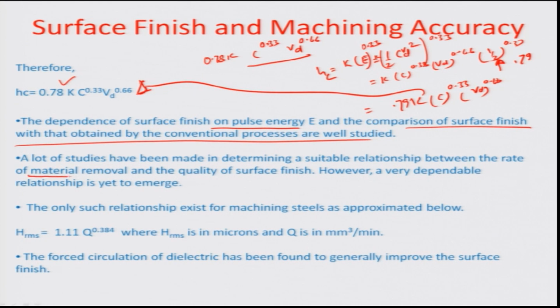because obviously a critical parameter for all the processes or processing related to any other machining processes is MRR, and the MRR actually would be determinant of what is the spark energy, for example, or what are the other associated mechanisms or parameters for the MRR to have a certain value. So, already there is a good mapping of the MRR into the various other parameters. These parameters could include, for example, the spark energy E, okay, and also maybe the rate at which the feed is given to the system, okay.